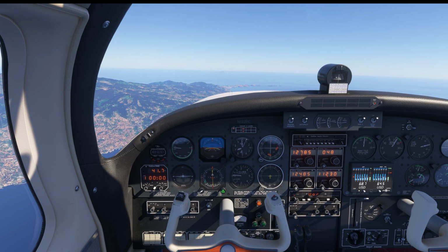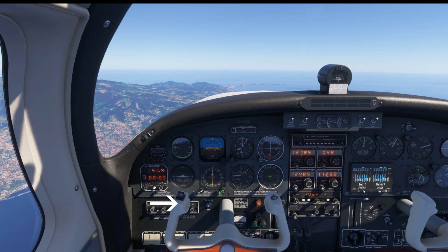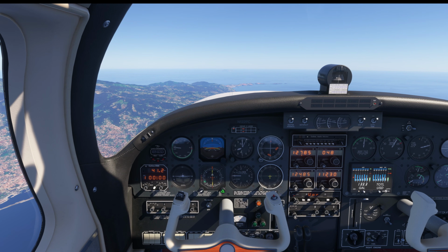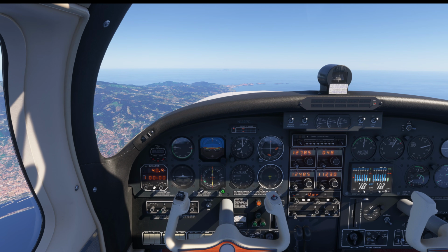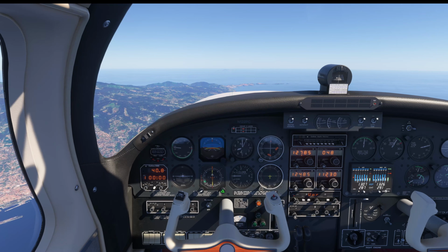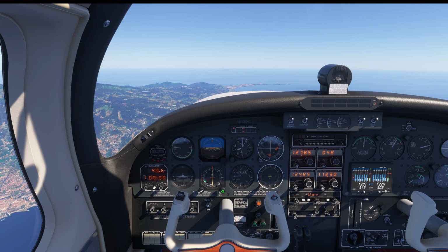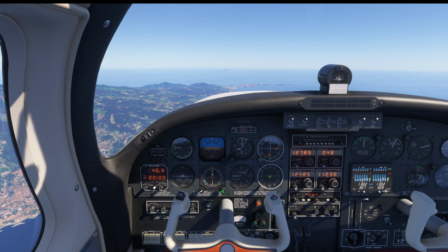Another hidden feature of the autopilot, and I mean literally hidden behind the yoke, is the pitch sync button. The only way to use it is through custom keybind, as explained previously. This button is especially useful when you want to change the aircraft attitude or take control of the aircraft briefly without completely disabling the autopilot.